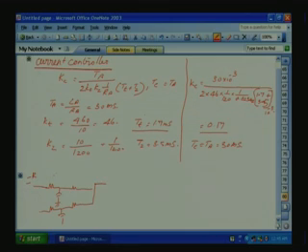So, we can choose this RC and this R. This RC based on our current filter time constant, that is 3.5 millisecond, and this also we can use 3.5 millisecond. Okay. Now, this will go to our PI controller.